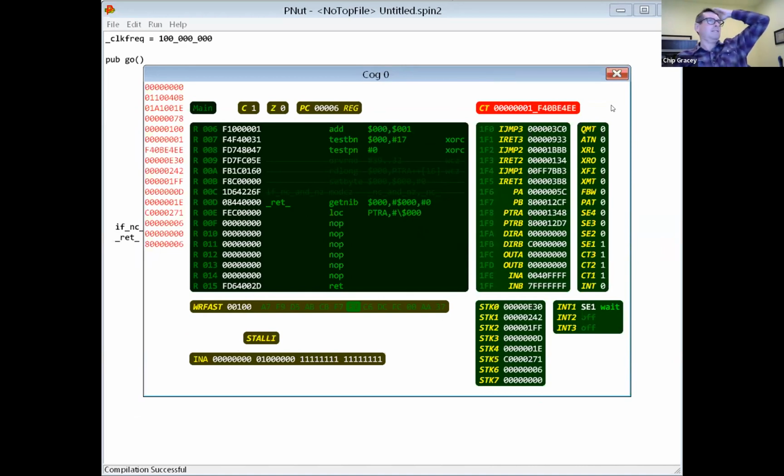And what's happening is I put in the debug thing that when a debug interrupt occurs, the likely thing the PC is going to want to do, because it has to display the information, and then it has to get some kind of input from the user, like a button press, like, okay, single step or jog or resume full speed. So before you have that, you can just tell the cog, hey, I don't have anything yet, go back to what you're doing. And then he calls back in 64 milliseconds. So we just give him this pause thing, and then he alerts us again with a whole new message.